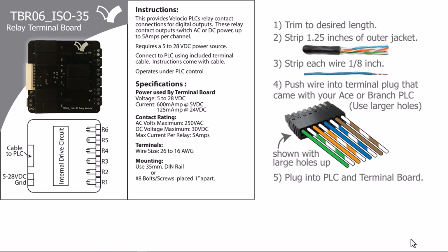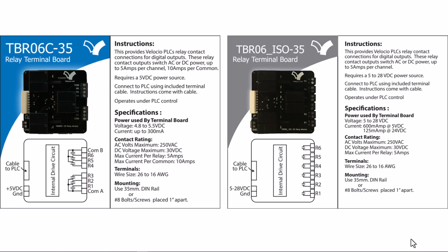Now you don't need to read through these specs, but you can also take the connectors that come with the Ace. Over there to your right, you see a black connector and it's got some different colored wires plugging into it. You just strip the wires and slide them in there. Now, I use strictly stranded tinned wire, 22 gauge, for almost everything I do in all of my training stuff. That's sufficient. You don't need larger conductor because it's just milliamps, thousandths of an amp. So you can wire up your own connections. You don't have to use this relay board, but it's a good idea.